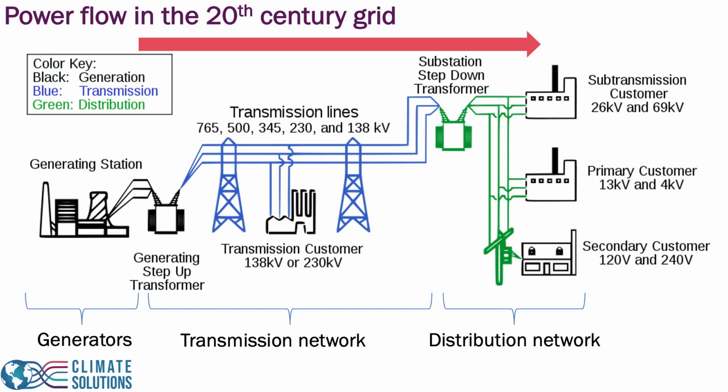Another thing to notice is that the generating stations produce power at a voltage typically lower than what is transmitted through the transmission lines. So there is a stepping up transformer that helps increase the voltage magnitude to make the generator's voltage compatible with the transmission lines. And you can see here in the figure the various voltage levels that are expected.